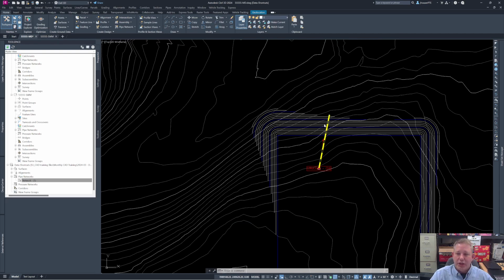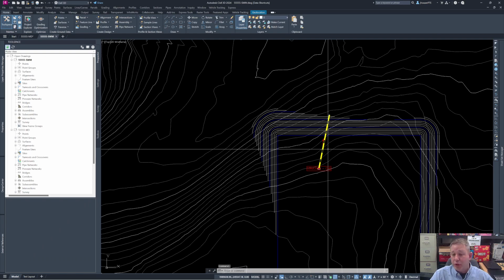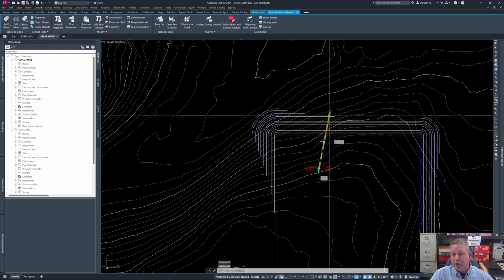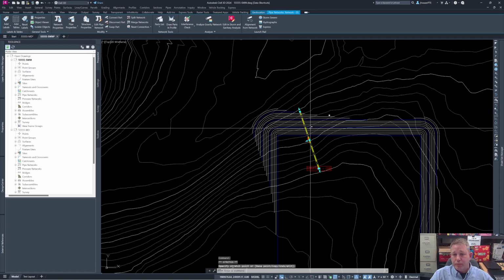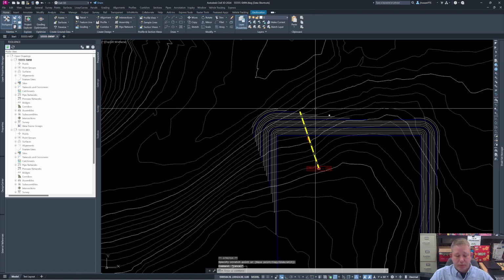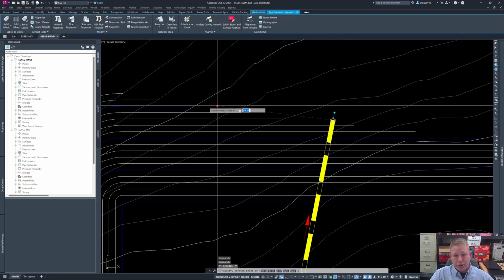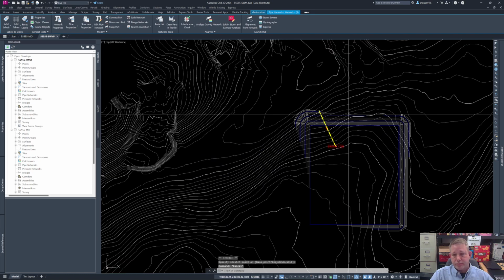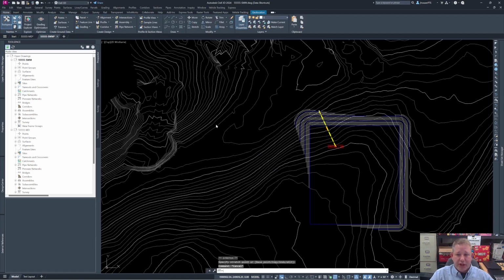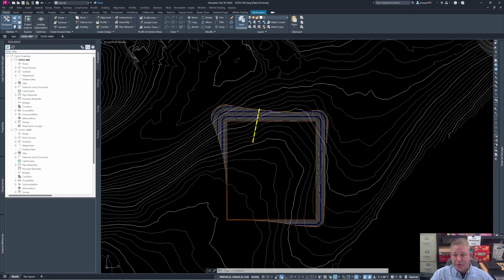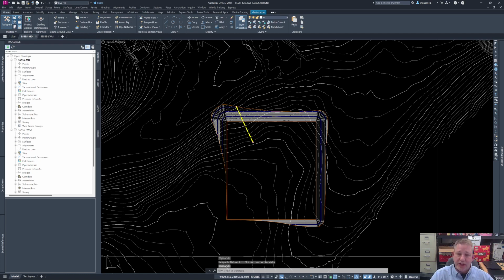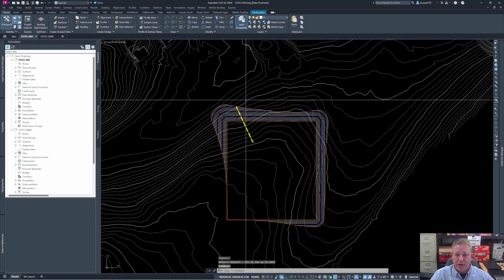So if I go back into the stormwater drawing, and I say, okay, I'm going to move this pipe. Oops. I'm going to move this pipe over to here. If I do a save, great. Got that in here. Now, if I go back to the MD, it should pop up a little warning, data shortcut has changed, and you hit your synchronize. So it alerts everyone when things change, and there you go, everything moved.